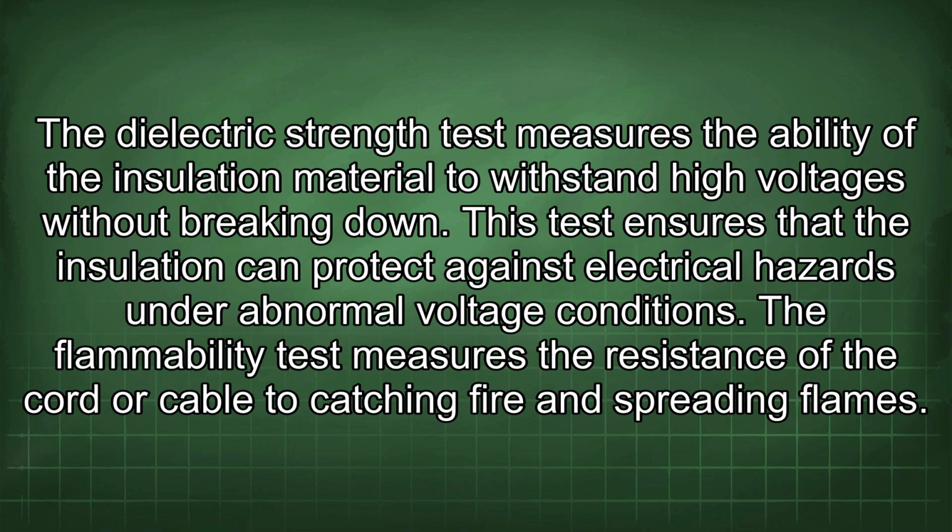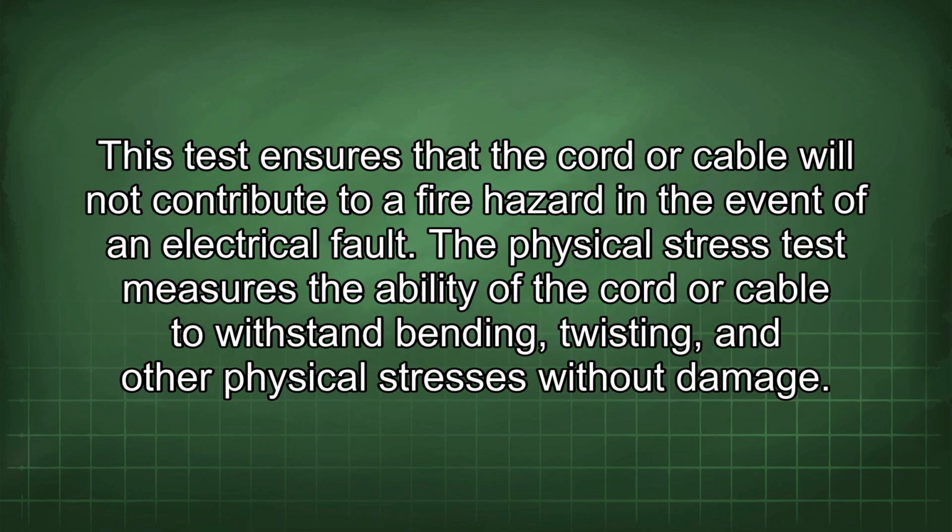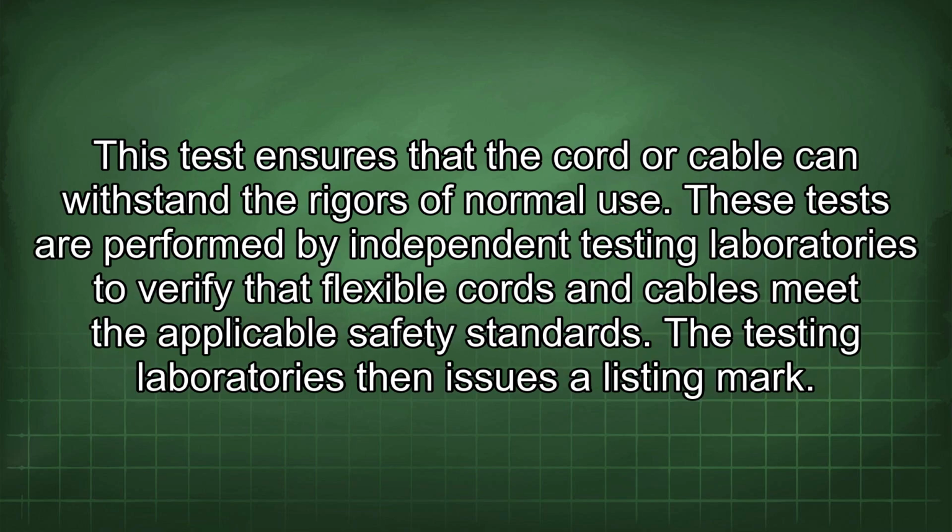The flammability test measures the resistance of the cord or cable to catching fire and spreading flames. This test ensures that the cord or cable will not contribute to a fire hazard in the event of an electrical fault. The physical stress test measures the ability of the cord or cable to withstand bending, twisting, and other physical stresses without damage. This test ensures that the cord or cable can withstand the rigors of normal use.